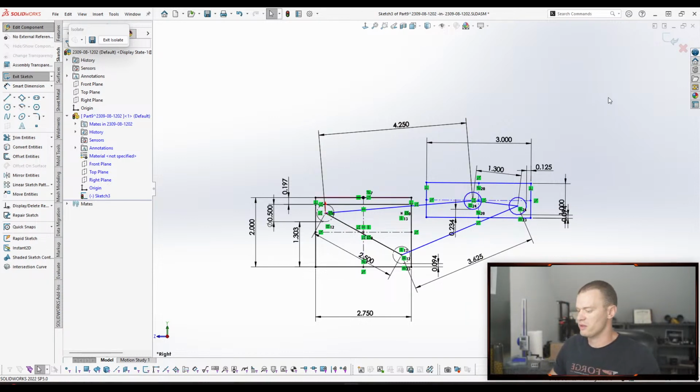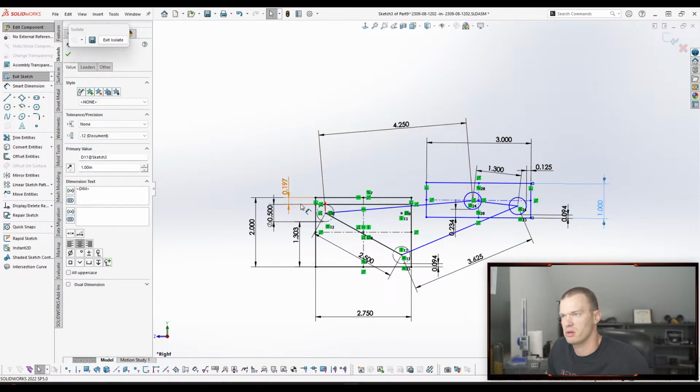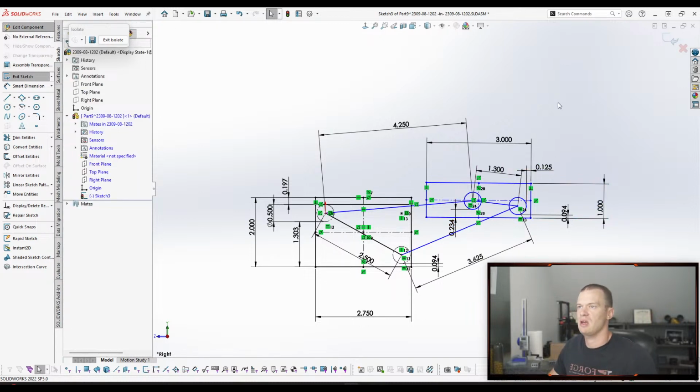So we're going to go back through and double check our measurements and see where we might be off. It could just be that one of our arms is the wrong length or something like that. Or it could be that when we were taking our measurements, we made some rounding to try and get whole numbers, and those rounding errors just compound on the mechanism to not quite line up where we wanted. So we'll take a look at it and go from there.